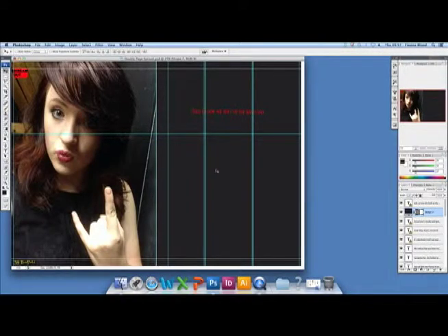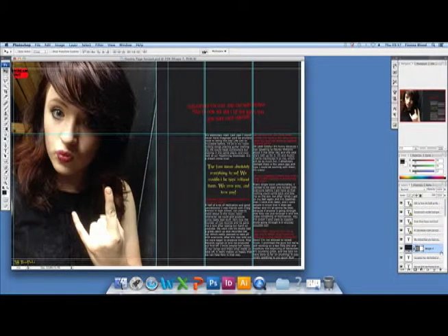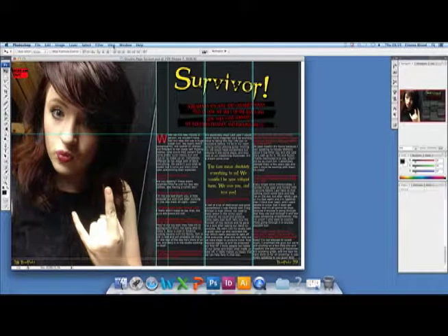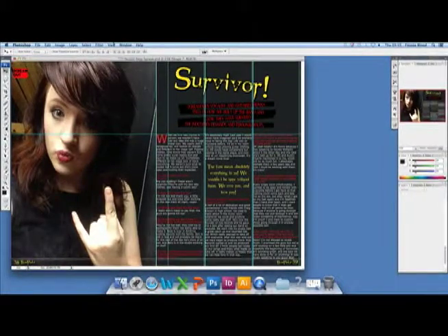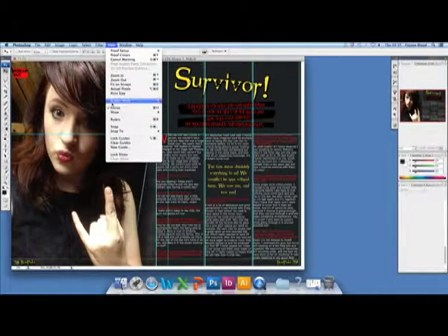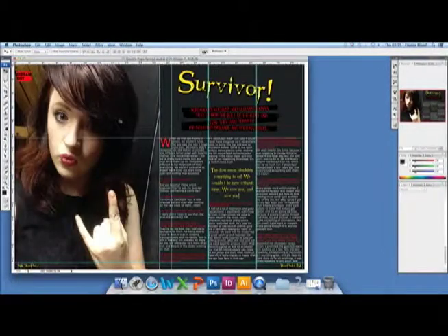To make adjusting things easier and more accurate, I took Snap off, put rulers on and also added some guidelines. To do this, I clicked View in the top toolbar, clicked Snap to remove it because it is automatically selected. I then had to click View again because the menu closes after something is done. I clicked on rulers to get them up on the screen. To get up guidelines, I clicked on the outer edge of the rulers and dragged from the top for horizontal rulers and from the side for vertical rulers, and then dragged them to the place I wanted them.